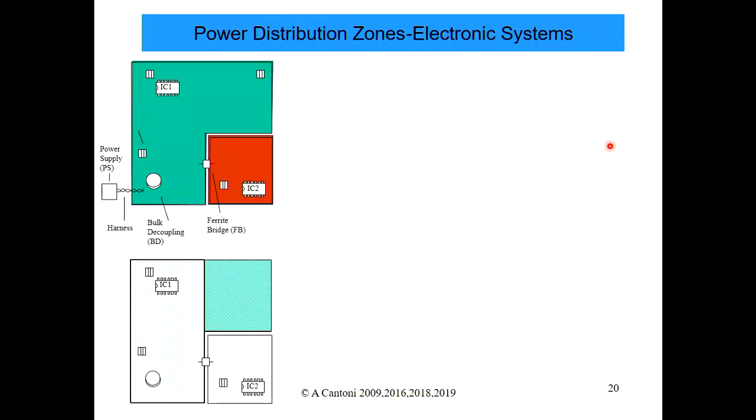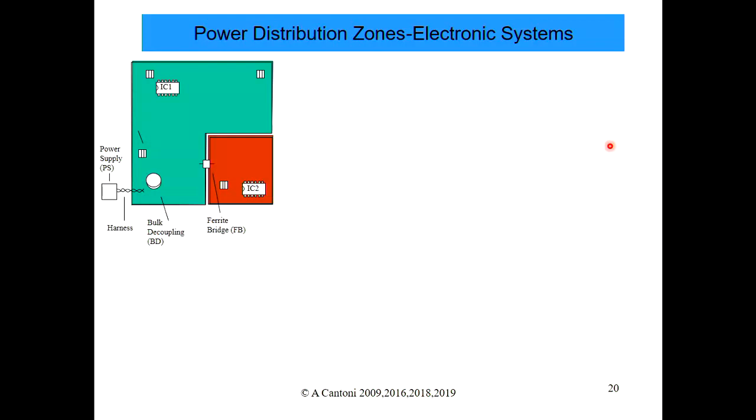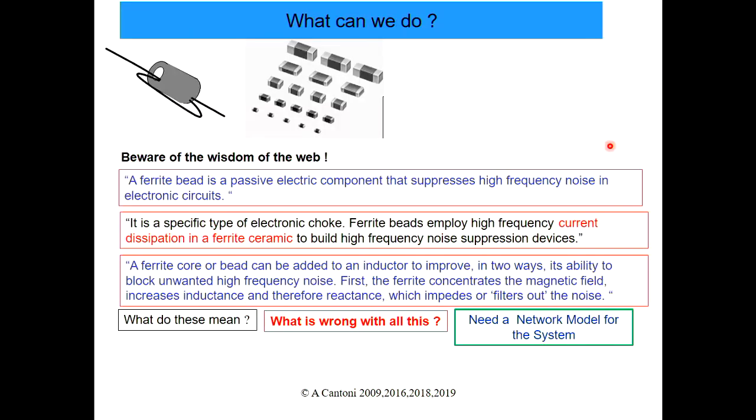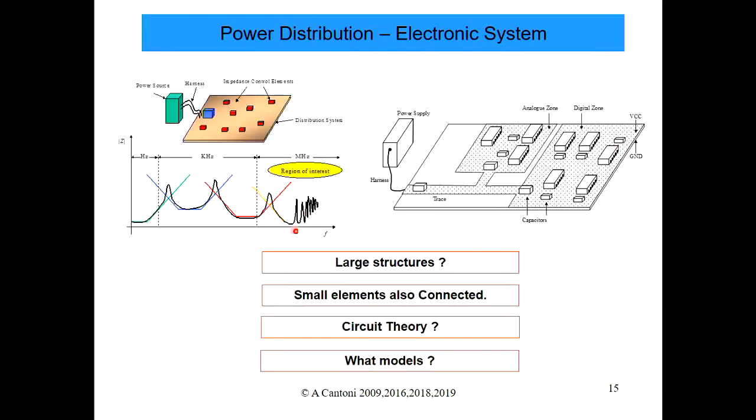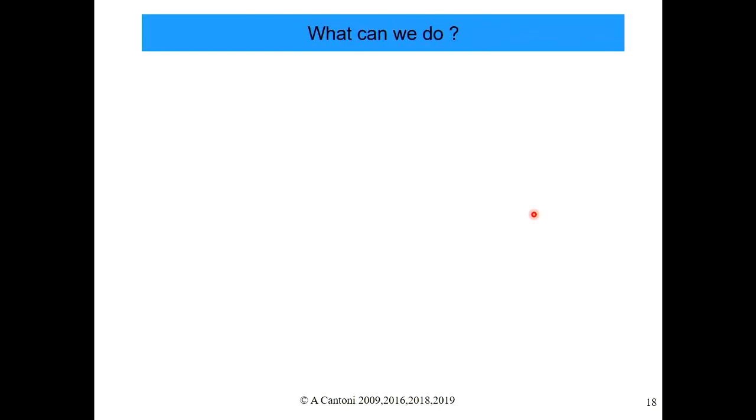So another, as I mentioned earlier, another aspect is modelling these high frequency resonances that occur on printed circuit boards in the project. Okay, so to do that, as I said, it's actual electromagnetic waves reflecting back and forth from the terminations of the actual power and ground planes. The electromagnetic radiation sees a different impedance when it comes to the end of the plane, so it gets reflected back. Talk more about that later. But that forms these resonances.